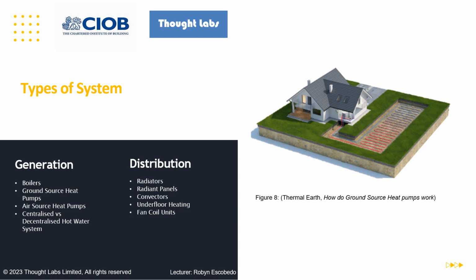So within these pipes we have a water refrigerant fluid which we call brine, and it absorbs this thermal energy from the ground and circulates it back to the heat pump. A compressor inside the heat pump increases the temperature and passes it to a heat exchanger. This transfers the heat to hot water cylinders, radiators, your emitters, and basically this is your space heating and your hot water for your building. Once the fluid has delivered the heat to your building, it's passed through an expansion valve, so it's cooled, and as you can see it turns blue, it goes back out again, and the cycle continues.